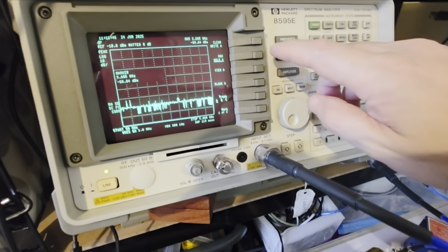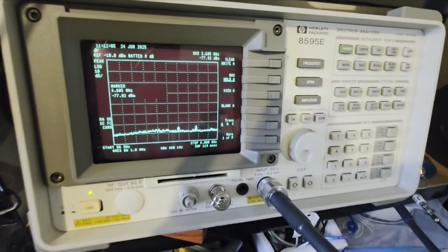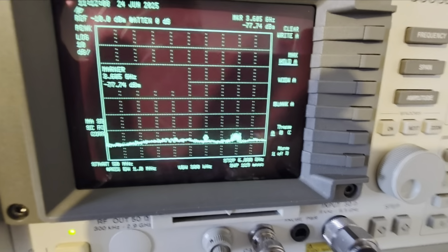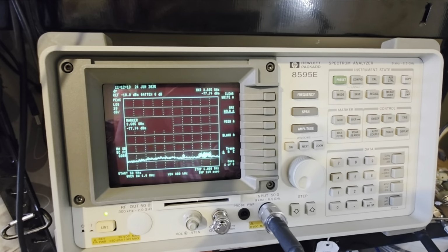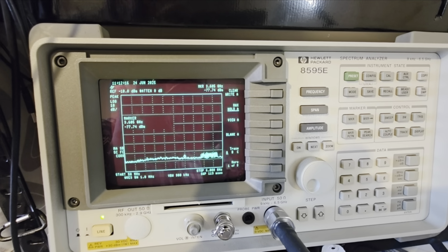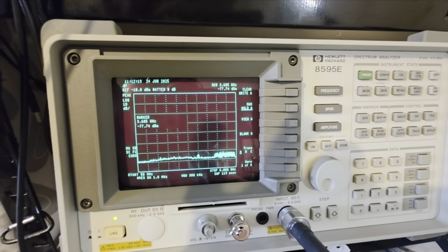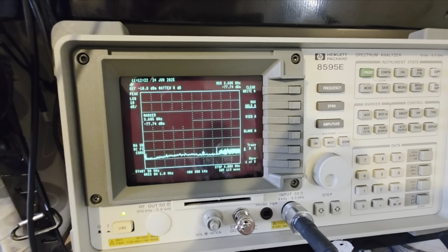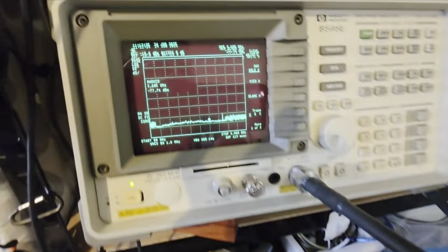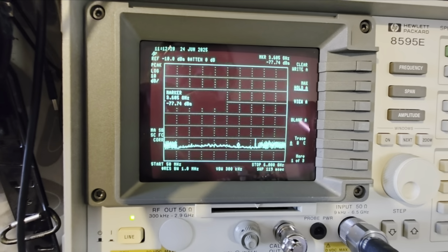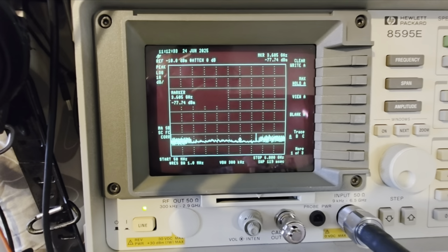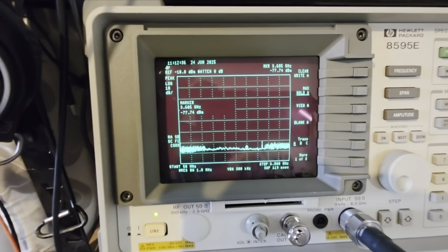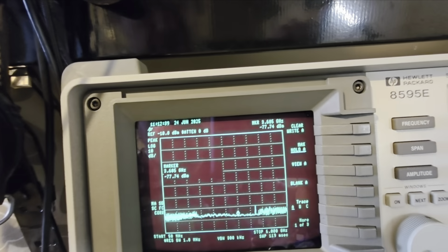I'm going to make another try and put 5 less. So max hold now. We're going to see. So it was 75, 5 more than the SDRs. And yeah, this one is going to do it as well. Another 5, 80. So 80 dynamic range.